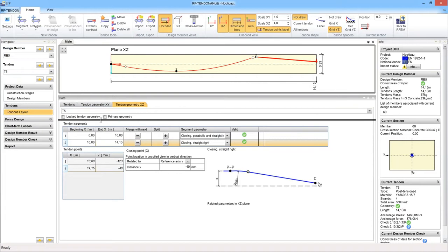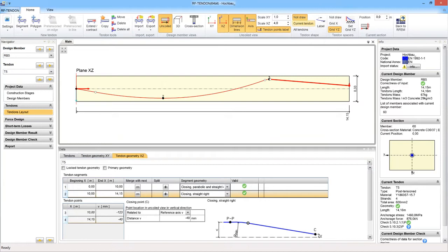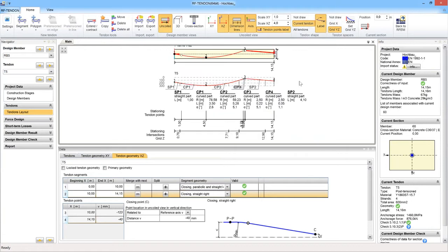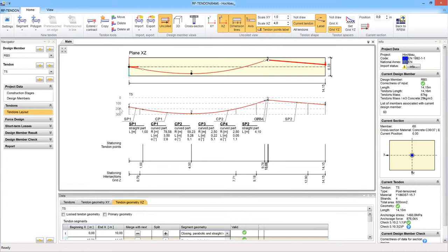The last thing which I wanted to show here is the drawing of the tendon along the length. Maybe I can switch on the labels, and then you can see that by defining these levels from the bottom of the beam, especially from the formwork, I can define the distance of the spacer which should be placed, with specific depth. For example, the spacer which is 300 millimeters will be placed here at 9.18 meters. So the program calculates it for you.